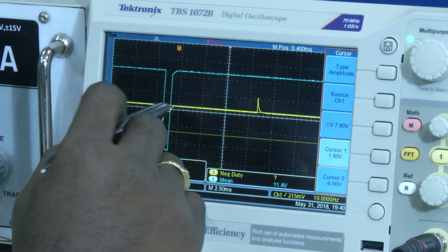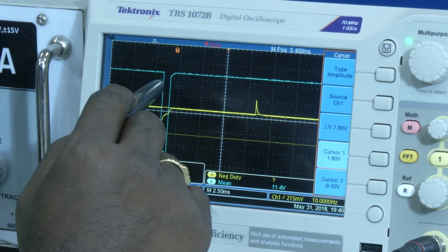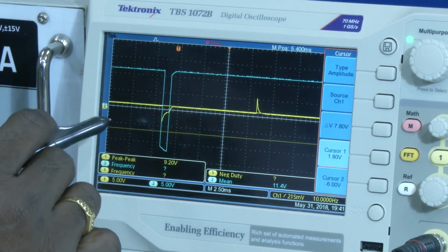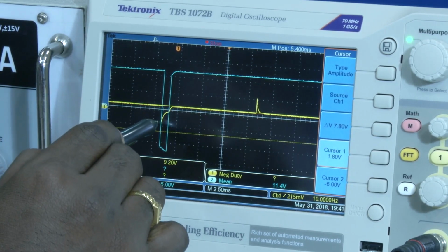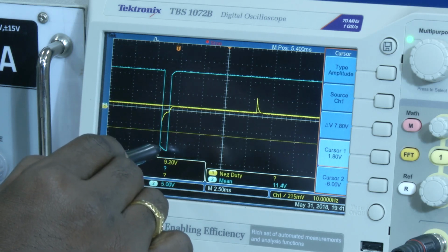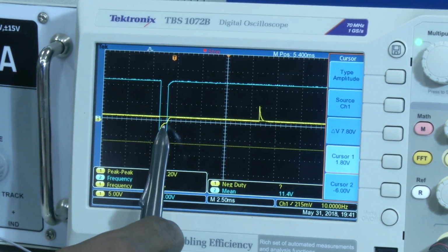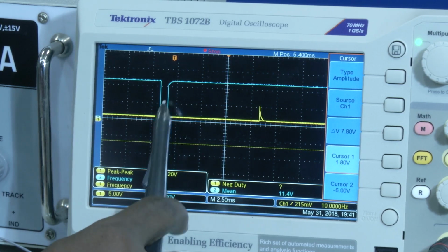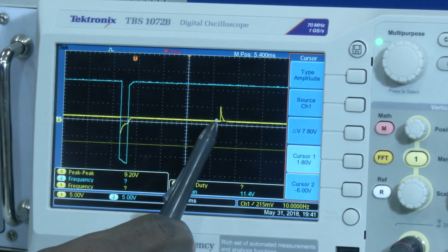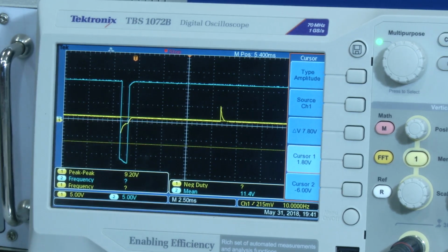So, here we can observe that whenever we are giving a negative pulse, right, what is happening is that because of the negative pulse from the function generator, the capacitor starts discharging, right. So, whenever it goes to minus 7.5, then it goes to minus VCC. And again when the value is greater than 7.5, it goes back to plus VCC, and this spike we can see because this is the voltage we are observing before the diode. After the diode, even that we cannot see, right.